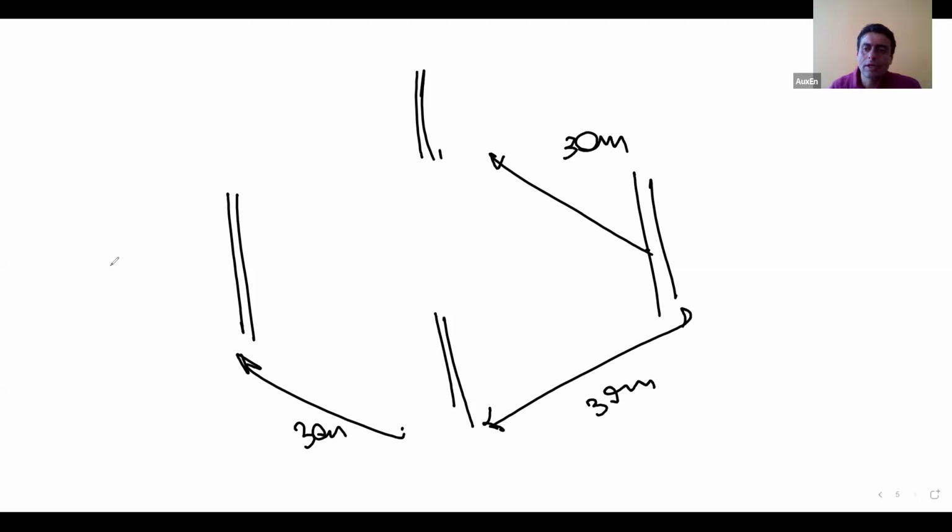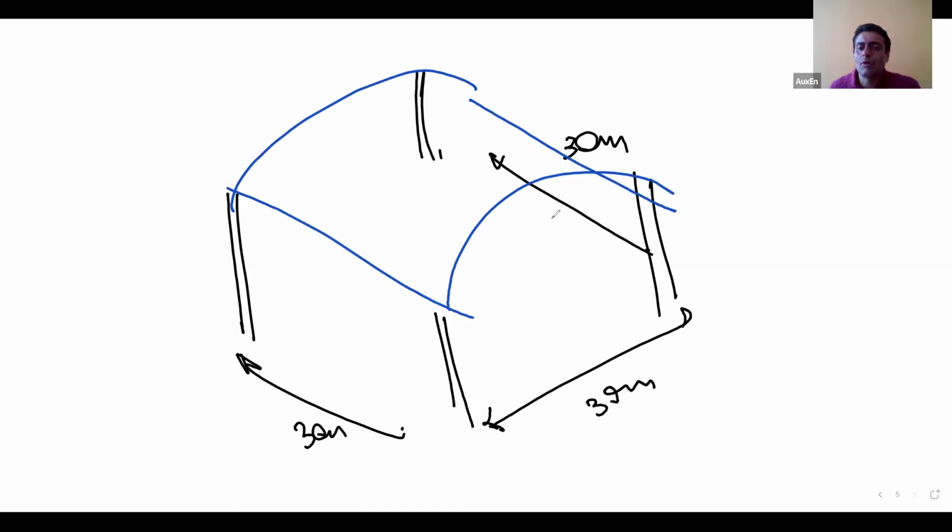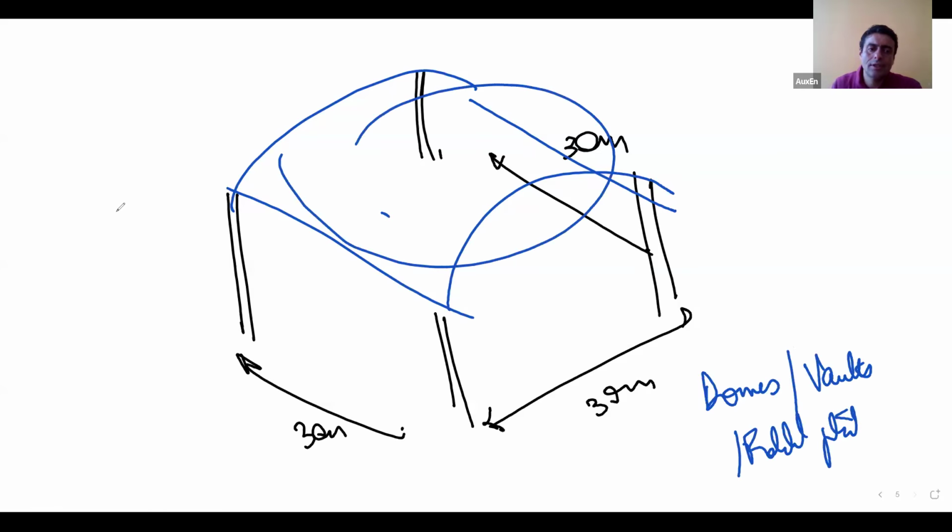So then what do we come up with? Either we come up with domes, or vaults or folded plates, isn't it? So in this case, the system has changed. We may come up with domes spanning in both directions or vaults or folded plates. Now the load transfer takes place from these elements, which we have chosen to take area loads, and then it might transfer to some beam-like things, and from there it might get transferred to your columns. Is it making sense?